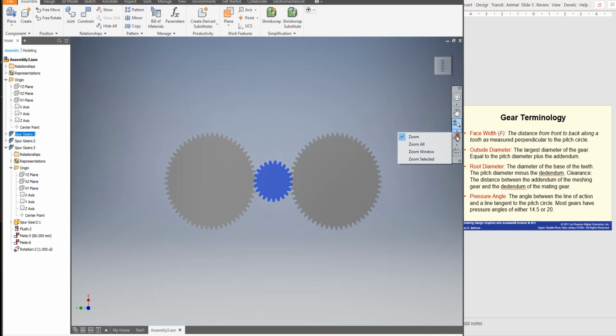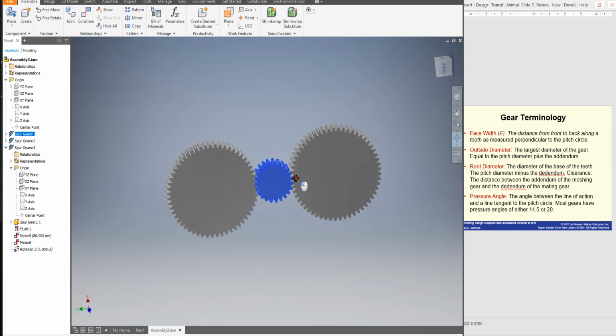Now, how can I demonstrate the motion? How can I record a movie? If you remember, I told you about the drive. How can I drive this motion? Actually, regarding assembly, done. But if you want to demonstrate the motion using drive, we have to add a constraint.